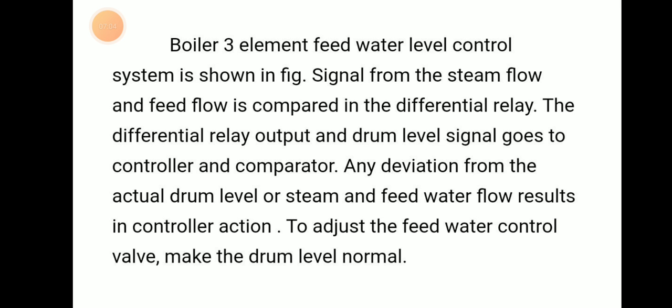Here we have the boiler 3-element feed water control system. The signal from the steam flow and feed flow is combined in a differential relay, and the differential relay output and drum level signal go to the controller and comparator. Any deviation from the actual drum level or steam and feed water flow results in control action to adjust the feed water control valve and make the drum level normal.